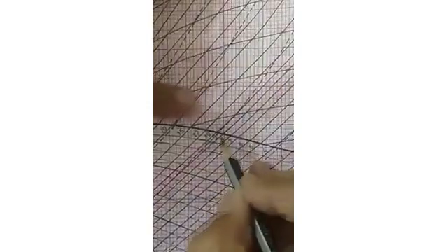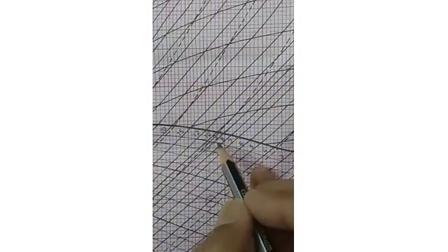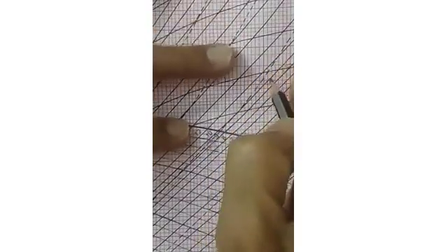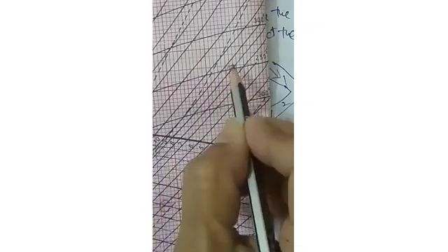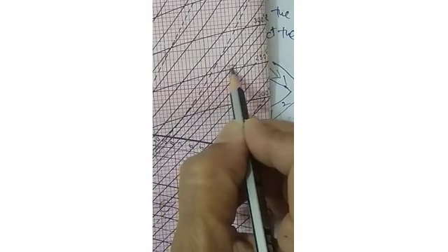So you can see that in the Mollier chart, these are the temperature lines, the horizontal lines. Where this 8 bar pressure is meeting the 250 degrees centigrade, you will get the point. This is the pressure line, this is the temperature line. So 8 bar and 250 degrees is meeting at this point. This is the first point.